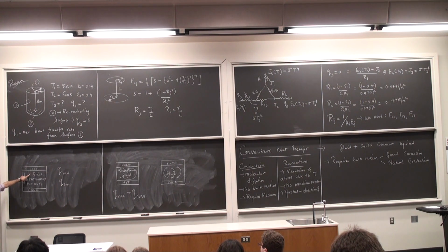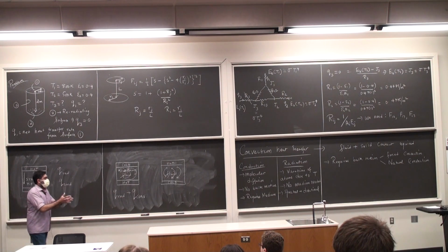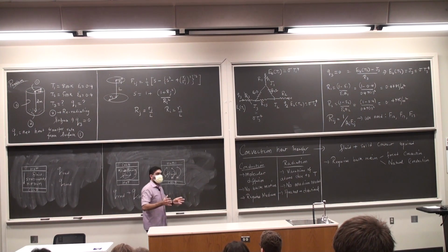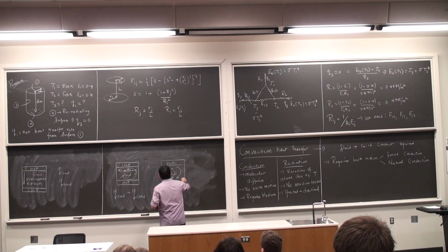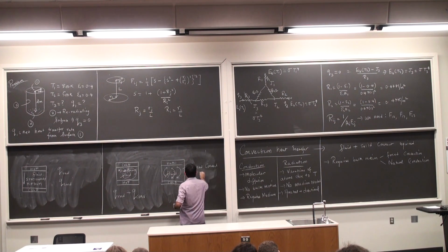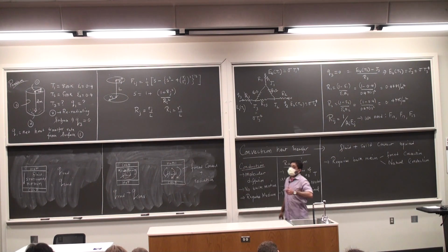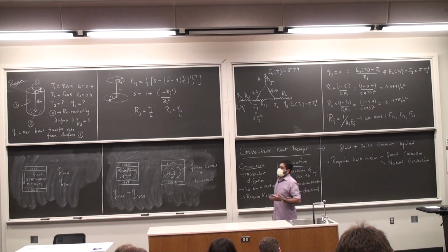Okay? And eventually, what can be shown, and we will be seeing it as we solve problems, is that conduction is nothing but the limiting case of convection. As the amount of bulk motion becomes smaller and smaller, the convective heat transfer coalesces to become conduction heat transfer. So in this case, I'm going to have forced convection plus radiation. And remember, convection is always conduction plus diffusion, advection. So when you say convection, it is implied that at the first